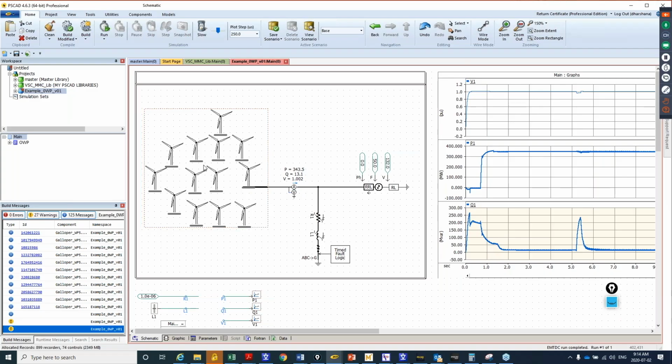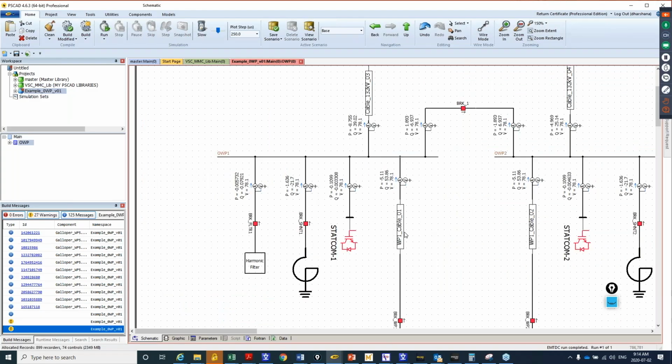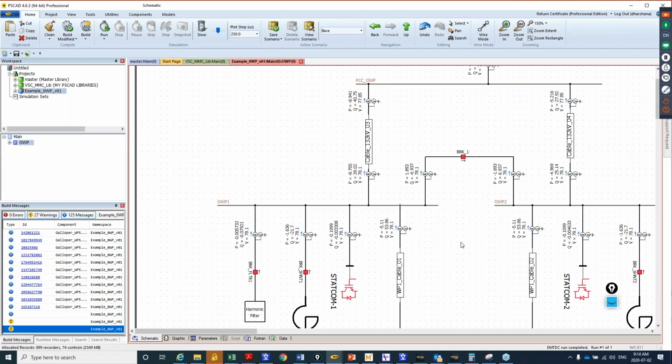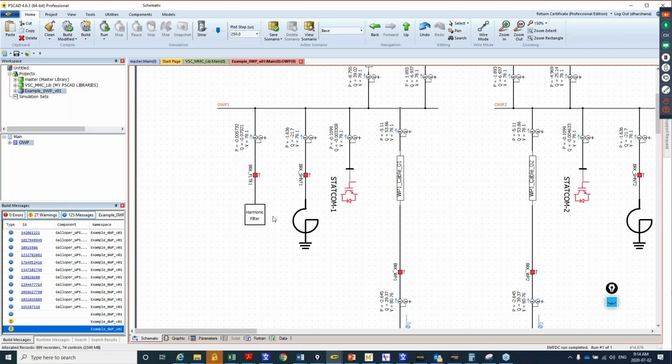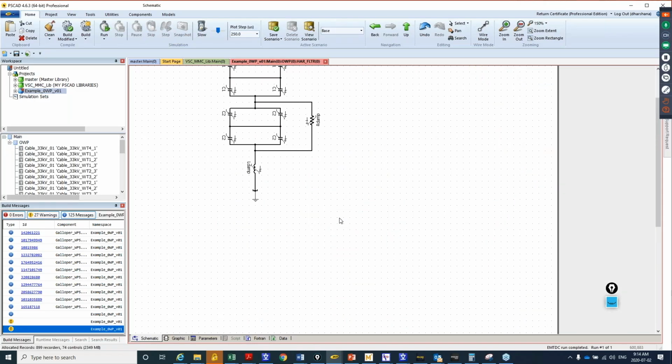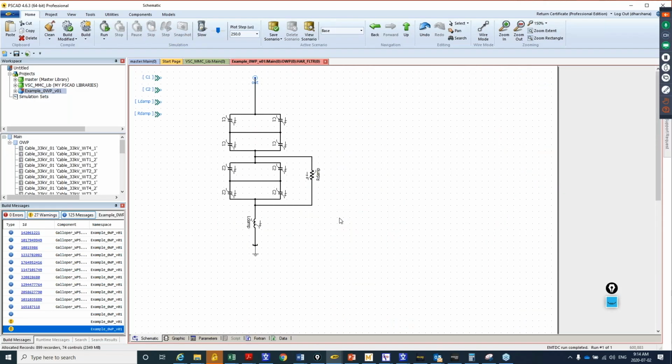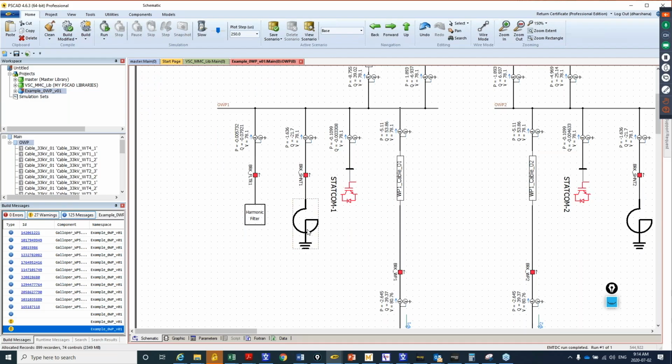But if I go inside this page, you will see the cables, the cable connections, some of the breaker arrangements in the substation, harmonic filters, the shunt reactors, and in this case, two STATCOMs, the STATCOMs that are necessary to meet your grid code from a voltage control point of view.